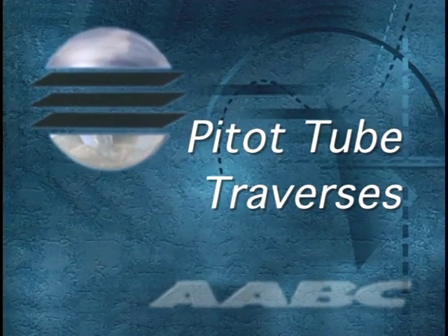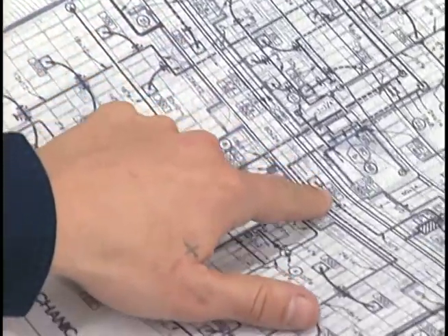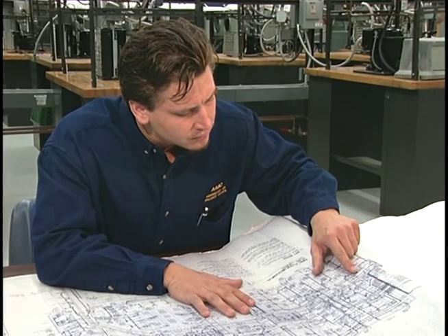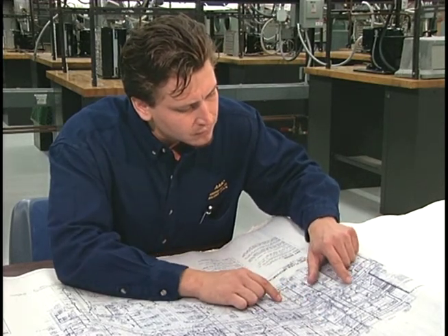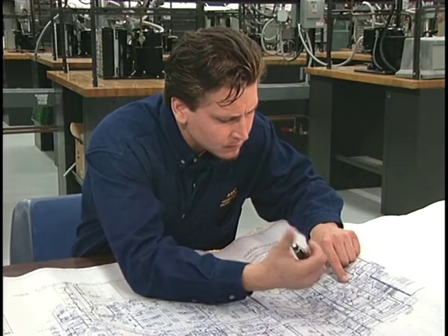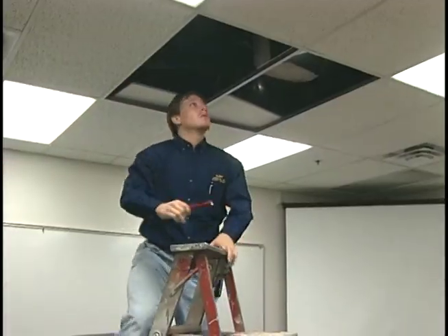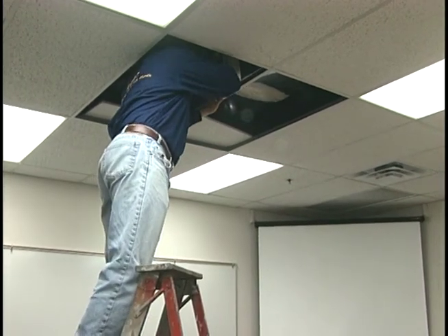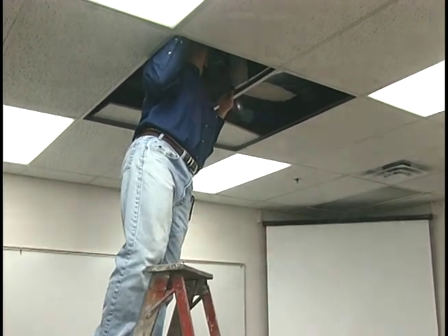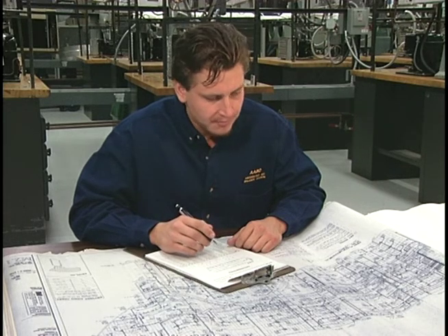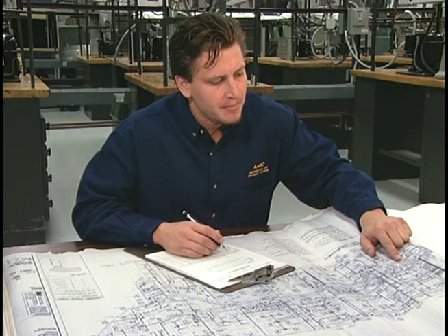Pitot tube traverses. During the preliminary preparations, the technician selected tentative locations for the pitot tube traverses. Because traverse readings can be inaccurate in a turbulent airstream, the traverse should be taken at least 8 duct diameters downstream and 2 duct diameters upstream of elbows, transitions, takeoffs, dampers, or any other restriction or obstruction that can cause turbulence. In the field, the technician confirms these locations or selects new ones that fit the criteria for taking accurate traverses. If the duct configuration permits it, the technician will take pitot tube traverses and static pressures at the main supply duct, outside air duct, return air duct, and all branched duct locations.